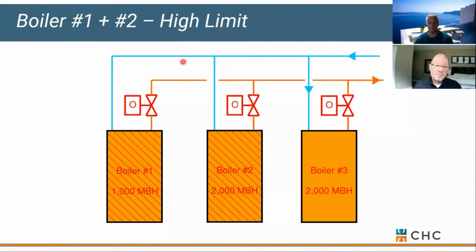Add automatic flow limiters to each boiler. Now, I agree, of all the choices, this might be one of the best ones, not so invasive. You could add a flow control to each one of these to create some resistance and help force water downstream. The trick is you've got system pumps on drives, and what do you set your auto flows to as far as flow rates go? You'd have to look at that very closely.